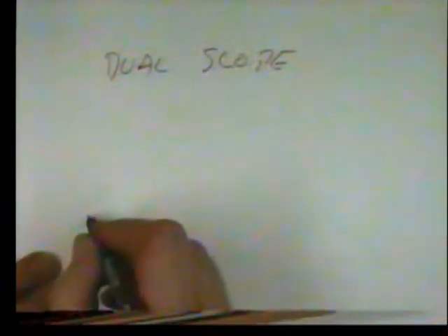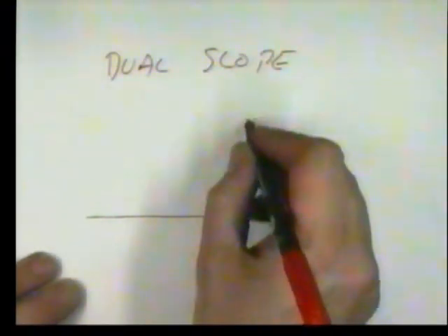There's a direct relationship between how quickly you can get voltage into your battery to get your car going and how much volts you're trying to apply to it in the first place. The greater the charging voltage, the quicker it will charge up. Now, a battery is no more than an extremely large-scale version of the humble electronic component known as a capacitor. And the whole basis of a dual slope ADC is it relies on this phenomena that you charge up capacitors, just like batteries. So how does a dual slope work? Well, let me draw a graph.